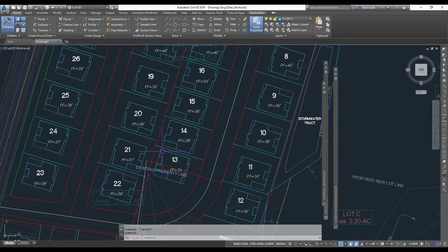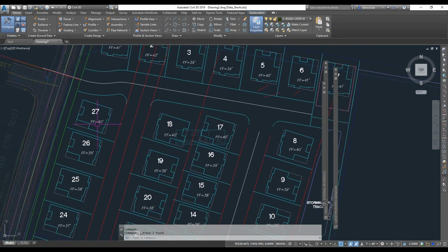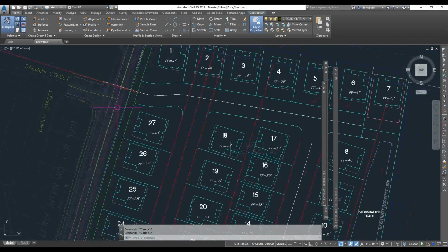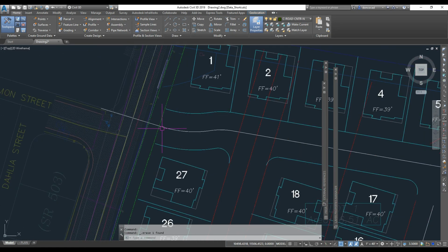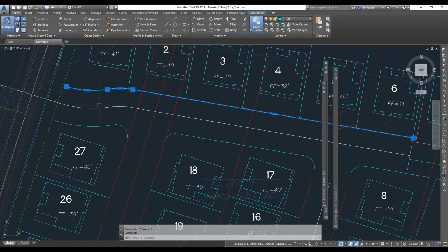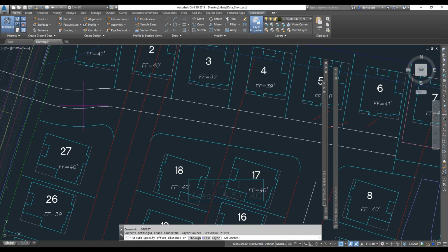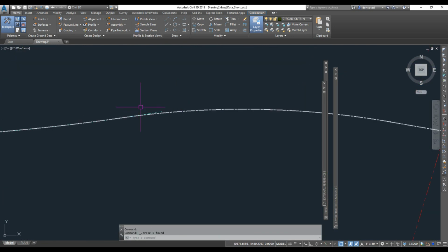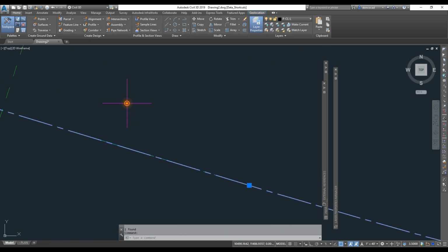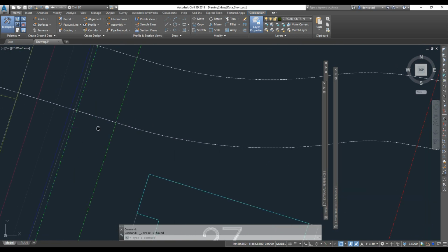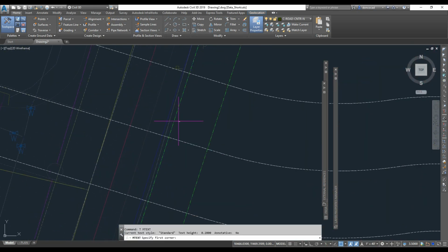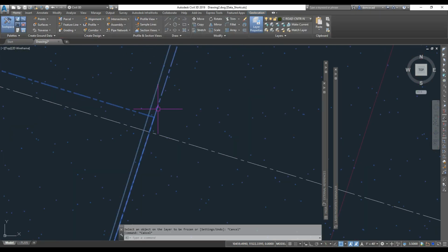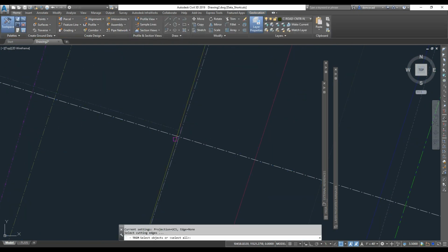When I create those alignments through the center line, poly edit, and then create an alignment from those, I will data shortcut those out and keep them and then use them, because later on in this project the first corridor crashes in fatal error. See, there's a good reason I fixed that. Look how sloppy that geometry is, or how far off it is. So we'll just trim all this up here. And oh yeah, we had 2 center lines, so pick one, go figure.